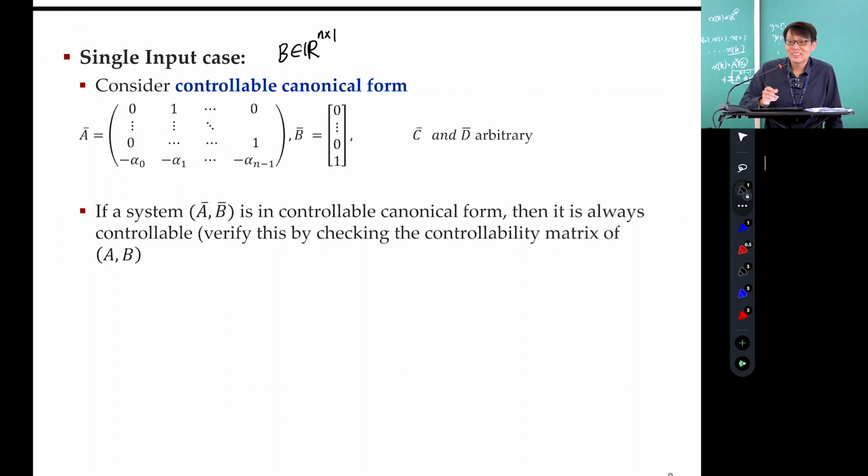No, right? When we do the transfer function to state space transformation, that thing looks like this, a controllable canonical form. If you haven't heard about this, this is nothing but a particular form of the A, B of this form. Okay, B is all 0 except the last one, and A is like this. I think you have seen this kind of matrix before. Okay, so all the diagonals are 0 except the last row has non-trivial entries, and the off diagonals are 1s.